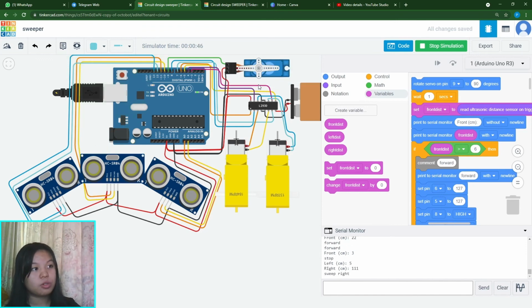It turns towards the right, sweeping right, and here we can see, okay, let's stop, 0 RPM, and then you see 180 plus RPM here, and the right motor was 137 RPM. So both are positive, moving forward, but the left motor is moving at a higher RPM, rotations per minute. This one is a lower rotation, so the left motor will overtake the right motor, and therefore they produce the motion of moving forward right. Okay, so that is scenario 2 combined with scenario 3.